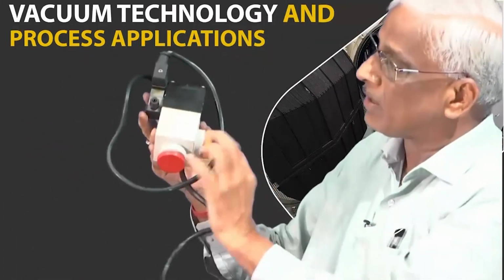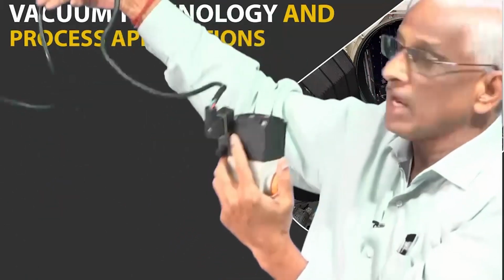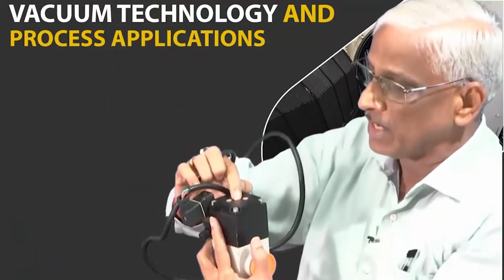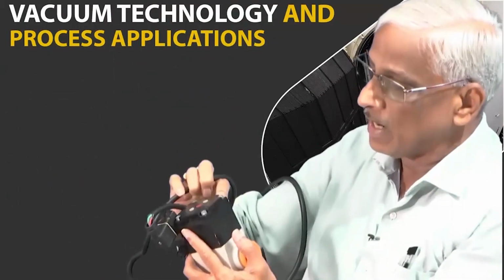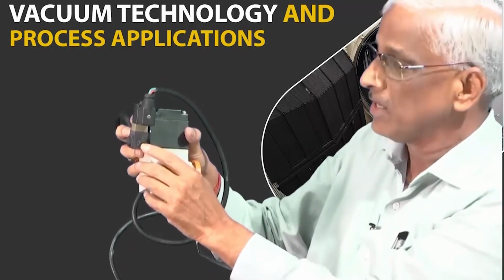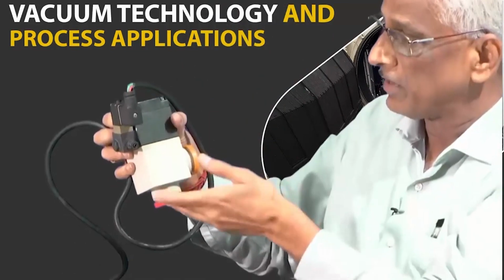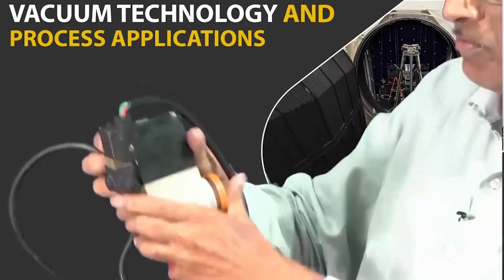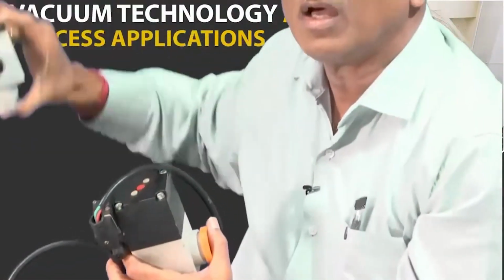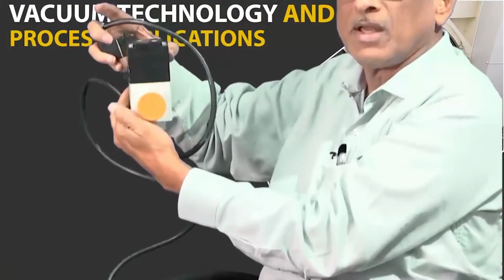And nowadays in process control, you can control it electropneumatically. So, same valve you can connect it to an electrical power supply. Whenever you want, then indicator will come out, so that it is open, and there is a pneumatic connection given here. So, that will be able to lift it, that bellow that is there, instead of manually doing like this, you will be doing the automatic things.